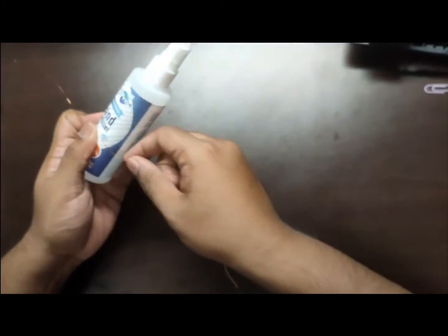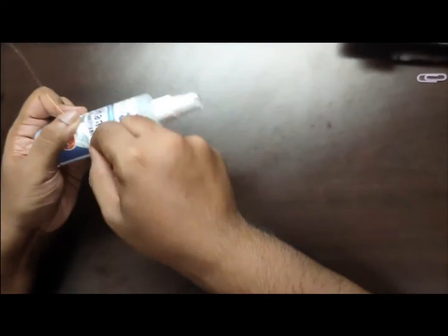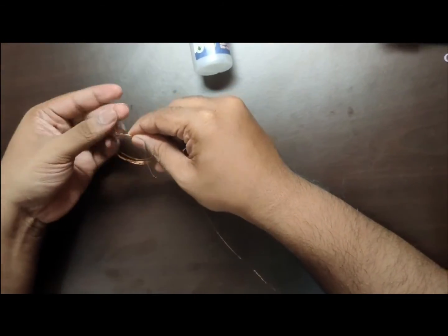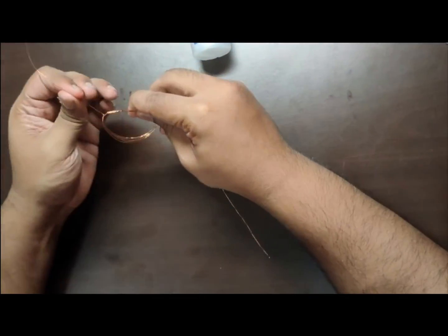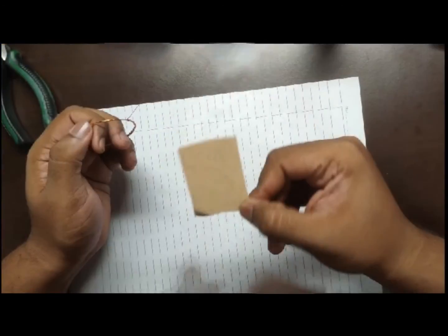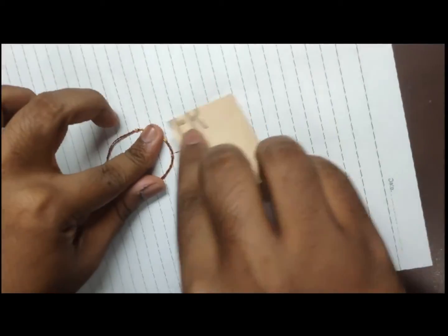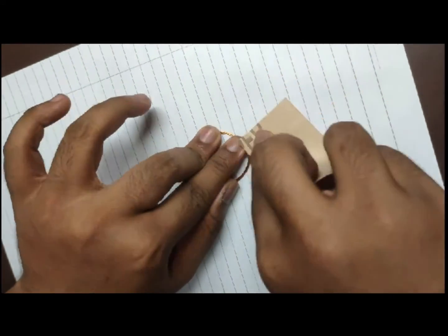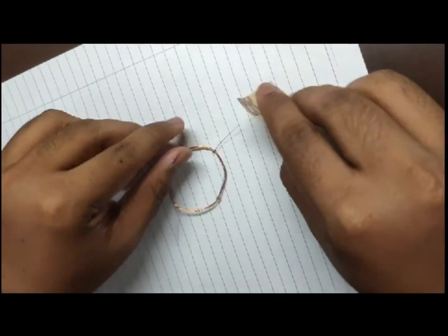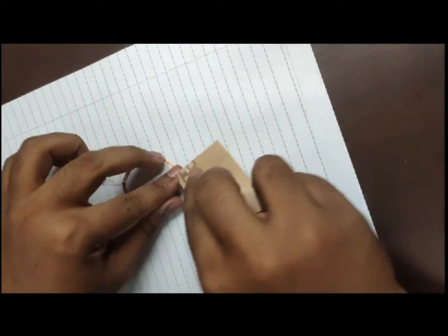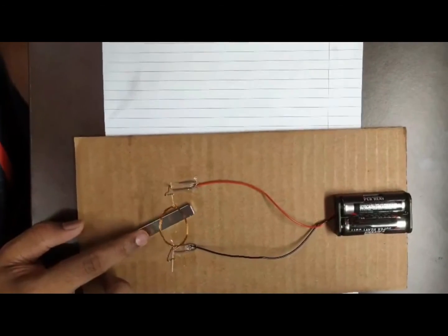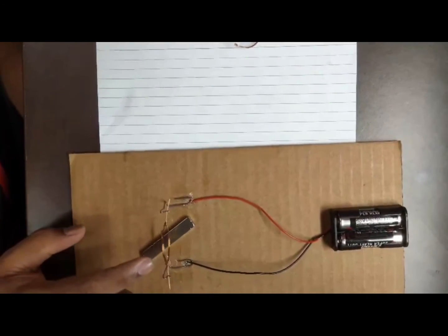The following step, we will be making the copper coil. We turn it around 5 times to come up with the copper coil. Then we tighten it up, making both ends the same length. Then, by using sandpaper, we rub off both ends of the copper coil. Finally, we will place the copper coil on both of the paper clips at each end and we will place a magnet under it. This is the output.